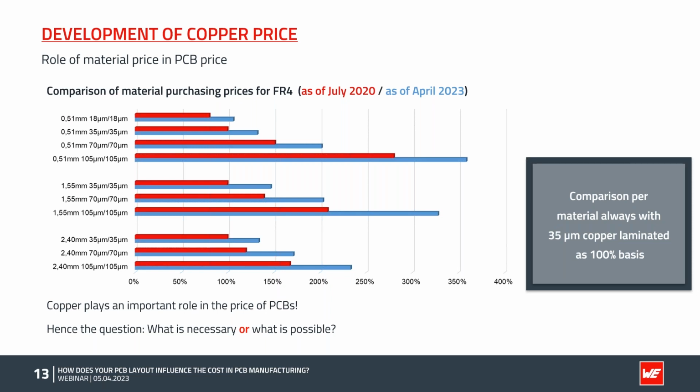What do I use? Because the more copper you have on the PCB, when we do the etching, the more copper we have to basically throw away after the etching, because especially for inner layers, this is still a subtractive process. And the less we have to throw away, the better it is. Therefore, use as much copper as you need and think if maybe 105, 70 or 35 is enough for your application. We have a lot of customers who came from the past, which always had in their specific requirements, even if they wouldn't need it, 35 micron on the inner layer. That was basically a standard.